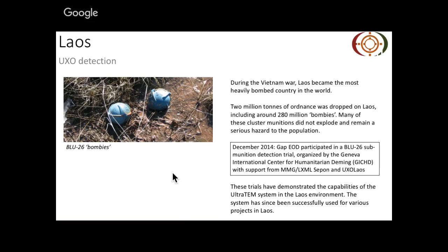Prior to going over there, everything was just done with analog systems, so there was no record of what was found. People could have been sleeping under a tree as far as anybody knew, because there was no documentation to show what had been done. There's no GPS positioning or anything. With items this small, we need very high precision real-time kinematic differential GPS, for 2 centimetre accurate positioning for bomb detection work.